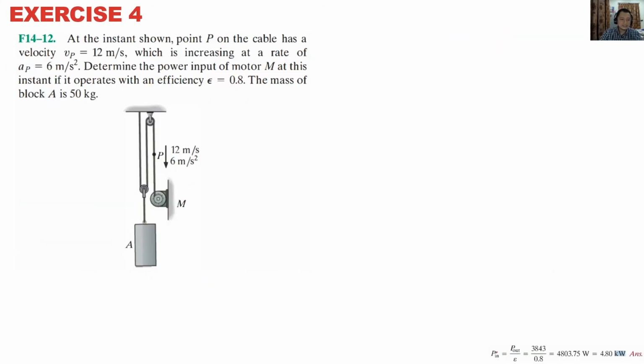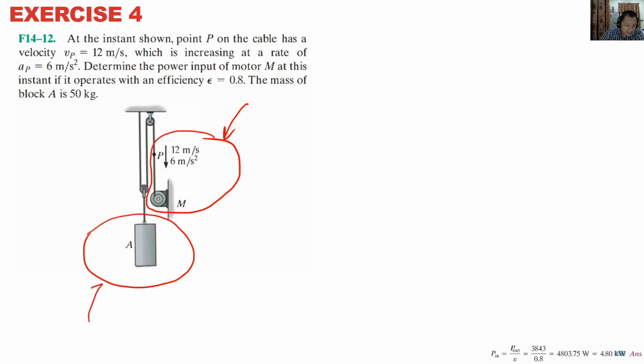Next question. You can do this on your own, but you have to really look at the system. You can ask yourself, do you want to analyze at the box, or do you want to analyze at the motor? You have to decide. If you analyze at the motor, solve the power as force times velocity at the motor.